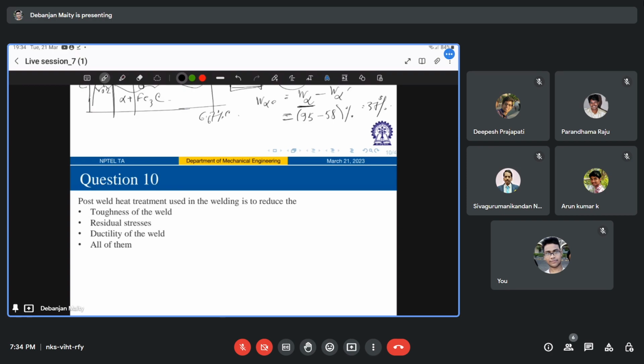However, during this stress relieving, you don't heat up above the upper critical temperature. You must remain under the lower transformation temperature range. For instance, carbon steel is heated to somewhere around 600 to 675 for some specific hours. I don't know what the hours are. Anyhow, this stress relief heat treatment reduces the risk of cracking in the weldments by reducing their hardness and also increasing the ductility.